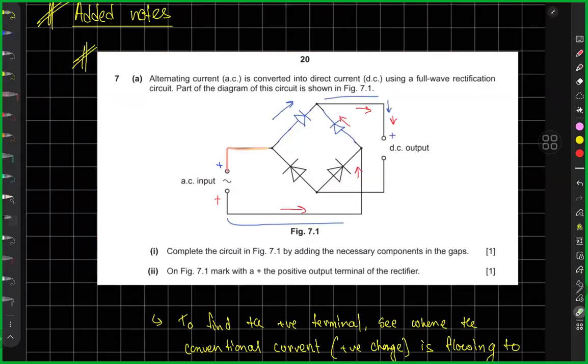Current comes in, conventional current comes in, and it can't go in here. That is given by the question. So I want a diode that allows current through this. So it's easy for me to say that here the diode should be forward facing, not backward. There should be a forward bias over here, so I allow current through this.